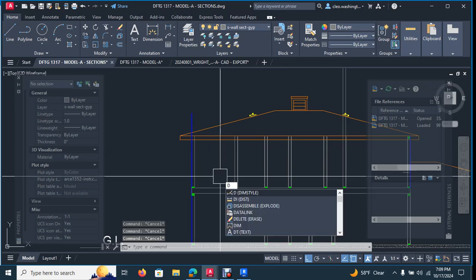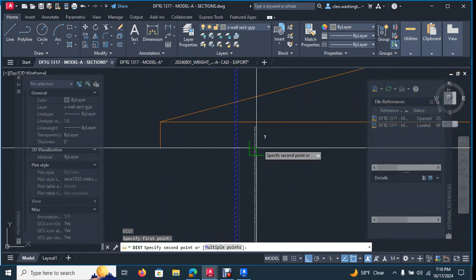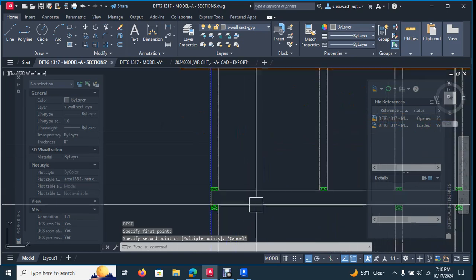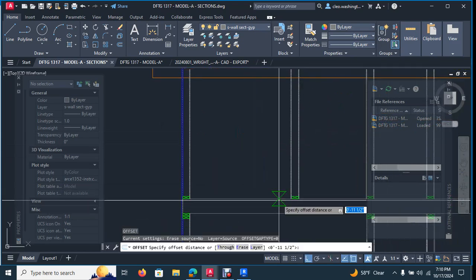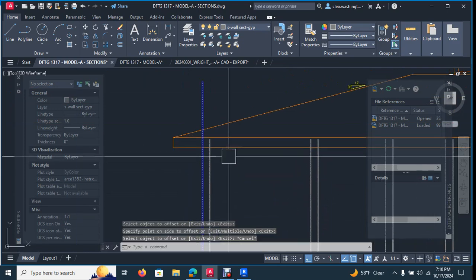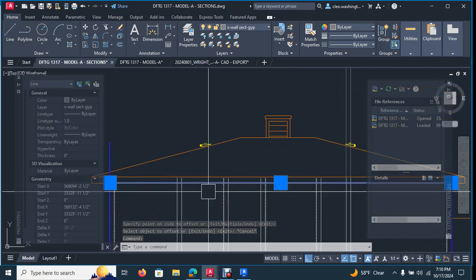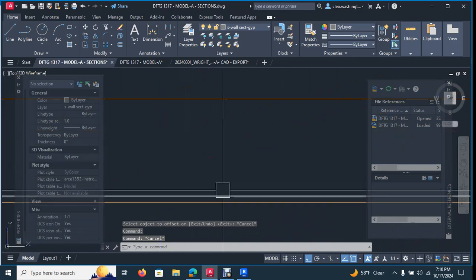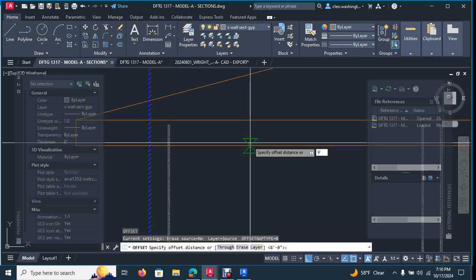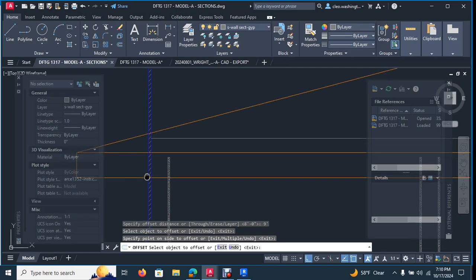So let's see how tall, maybe we'll have 8 foot at the second floor. 8'6". Yeah, maybe we do the second floor at 8 foot. Offset, enter 8 foot. Do I like the 8 foot? Or maybe let's do 9. Let's see what 9 looks like. Offset 9 foot. So offset the floor 9 foot. What we're doing here is we're setting the ceiling heights. Okay. Yeah, let's go with 9 foot.